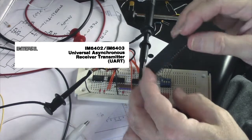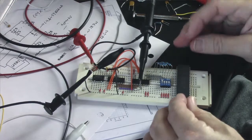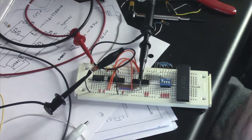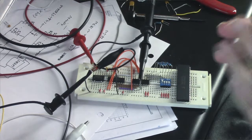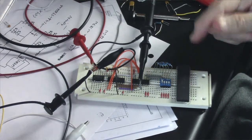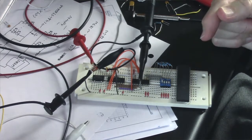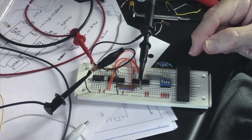Today we're going to take a quick look at a baud rate generator for a 6402 UART. That's that chip there, which I'm planning to use in a project. And so I need to be able to generate different baud rates. Now that takes as input 16 times the bit rate.